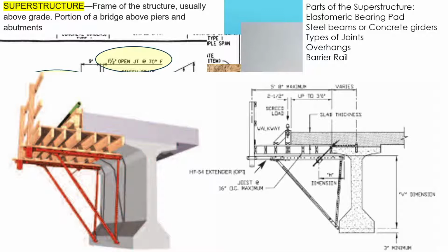Overhangs. This is how the overhangs of your bridge deck are poured. These are designed to support the edges of the slab and always the means of paving said road, whether it be a Bidwell, Razorback screed, Hogg screed, whatever. Here in this case, it's going to be a Bidwell with your pipe rails, and these have to be engineered.